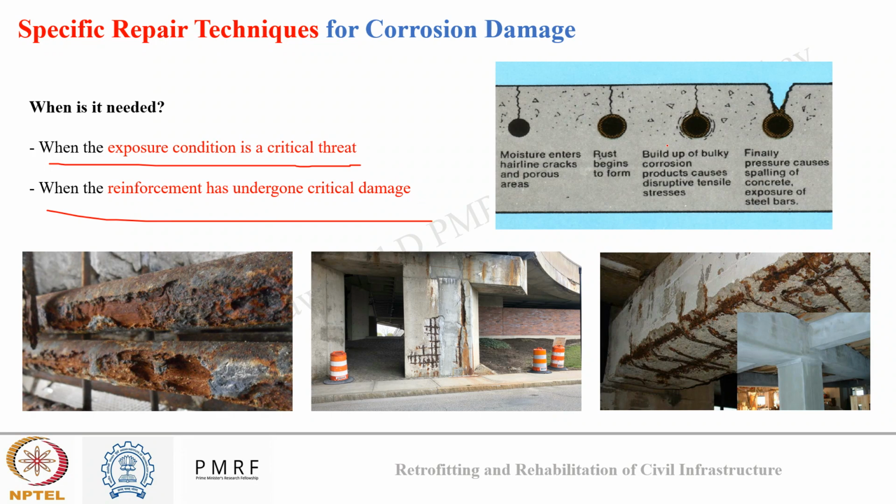As shown in the image, when there is corrosion damage, what happens? First, there is cracking inside the concrete. Now, due to buildup of corrosion product on the surface of the concrete, my crack will expand and take a bigger shape, and as soon as my steel reinforcement is more freely available to aggressive ions from outside, it will corrode more and can be more severely affected.